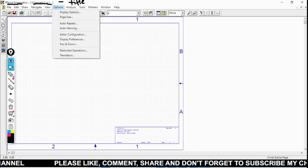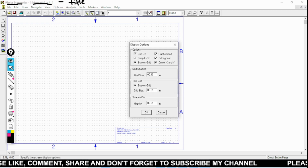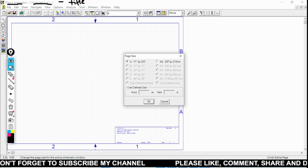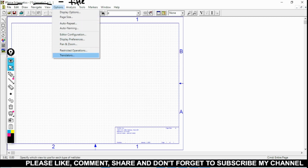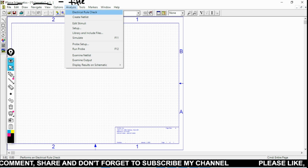Then the next one is called option, where we can see the display options, how to display it, how many grids there will be, what the size of that grid will be, and so on. Then you can go for page size. What will the page size be? Is it to be A4 or A, B, A3, A2, A1, and so on. So we can select from here. Then there are other options called pan and zoom and so on. Then there is analysis. This is very important, where we are going to use the electrical rule check. This electrical rule check is very important when we are checking for errors, or if there are some warnings, and that's all.